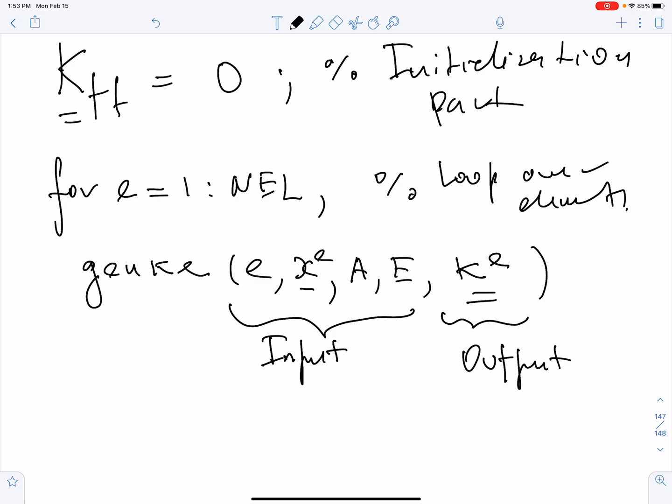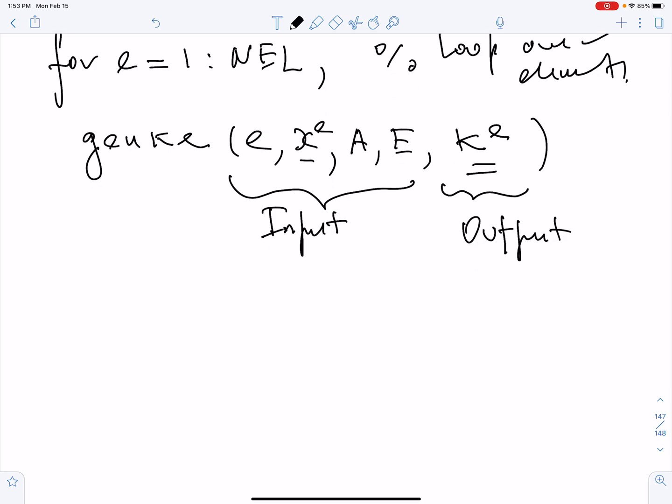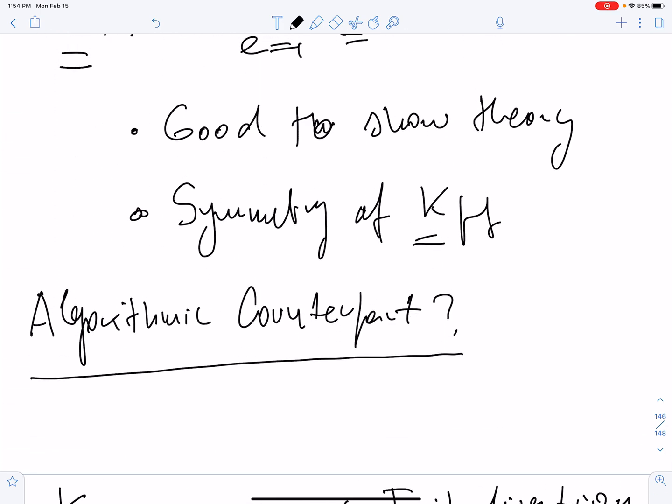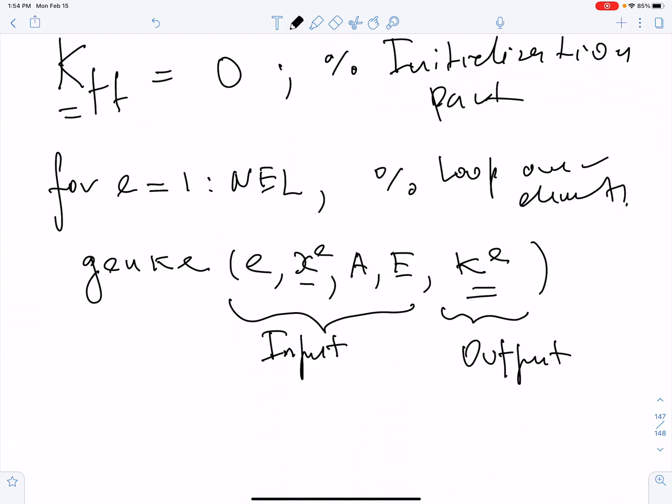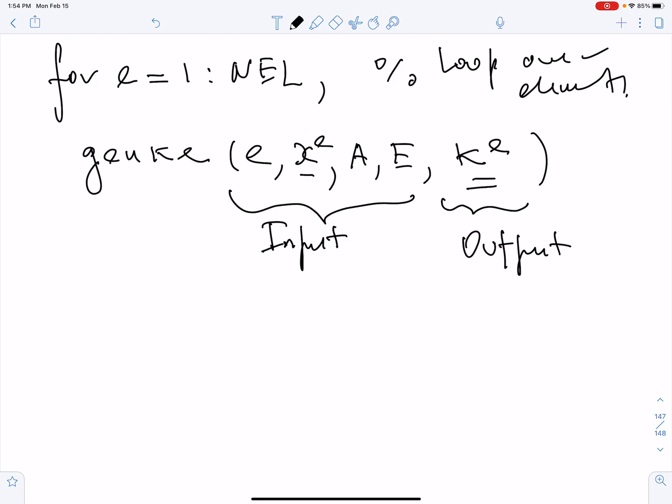And so now you have KE, and your job is to now populate KFF. So algorithmically apply these transformations by BF. As far as pseudocode is concerned, it's actually much simpler than you think. You isolate each individual stiffness matrix. Now you need to loop over the degrees of freedom, for each row and for each column. So you can imagine there's another for loop where some index I goes from 1 to 4.